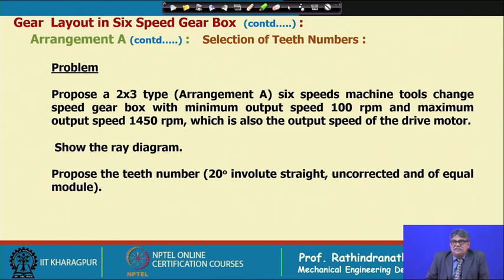And designing such gears, take the smallest gear with maximum torque. Materials will be same for all gears. So, take the smallest gear with maximum torque. This means that we have to find out for which smallest gear that maximum torque is there, and then if we design that one, all gears would be taken of same module and same width. Teeth number will be different, materials is also same.